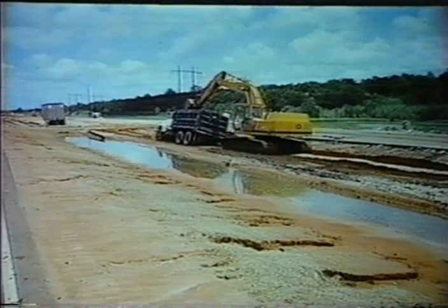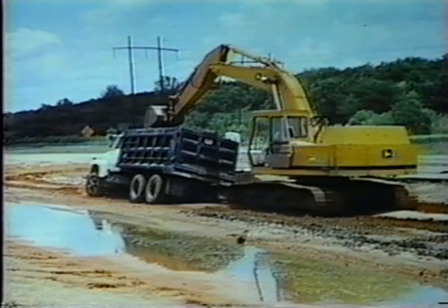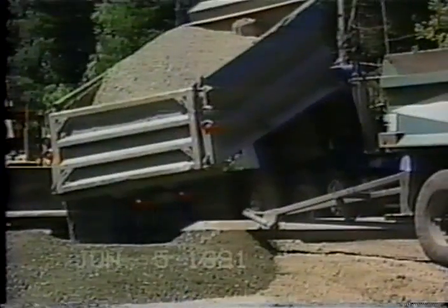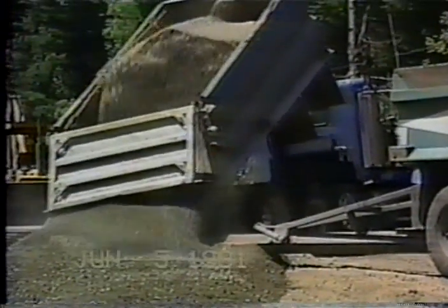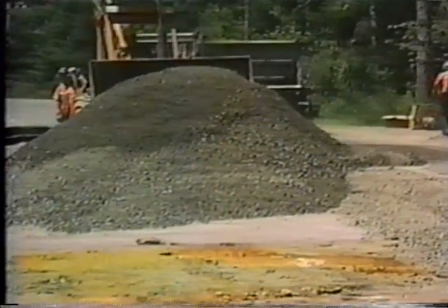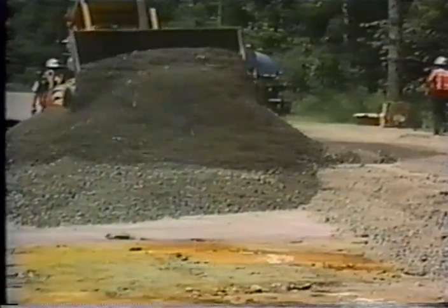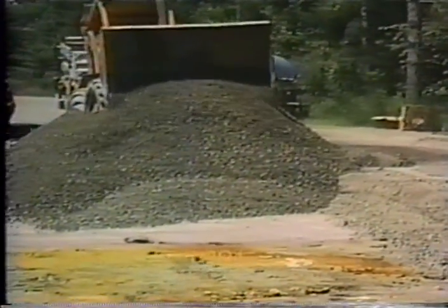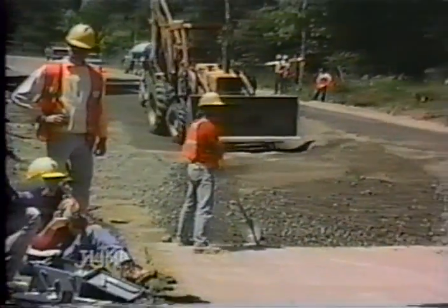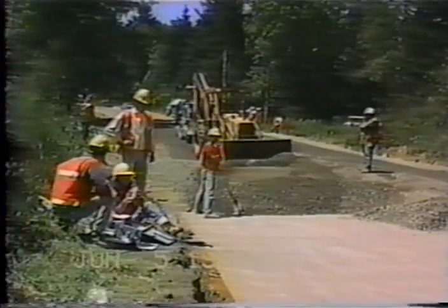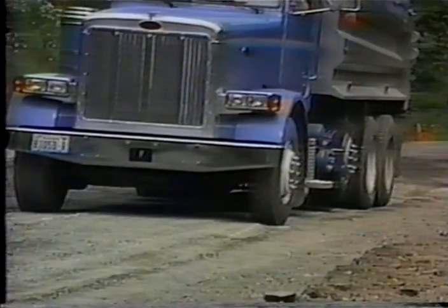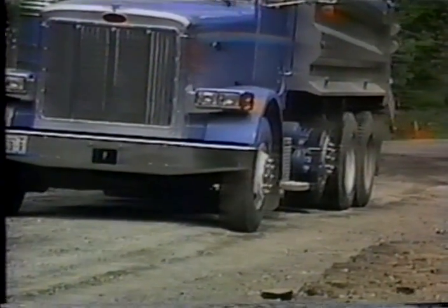It is important to keep rut formation to a minimum to prevent local shear failure and the subsequent contamination of base material. One possible way of achieving this is to increase the thickness of the base layer in order to better distribute local loads. However, increasing the thickness of the base layer also considerably increases construction costs, especially the cost of replacement fill. Use of a geosynthetic to separate, reinforce, filter, and drain reduces the thickness of fill usually required and offers numerous advantages for paved and unpaved roads.